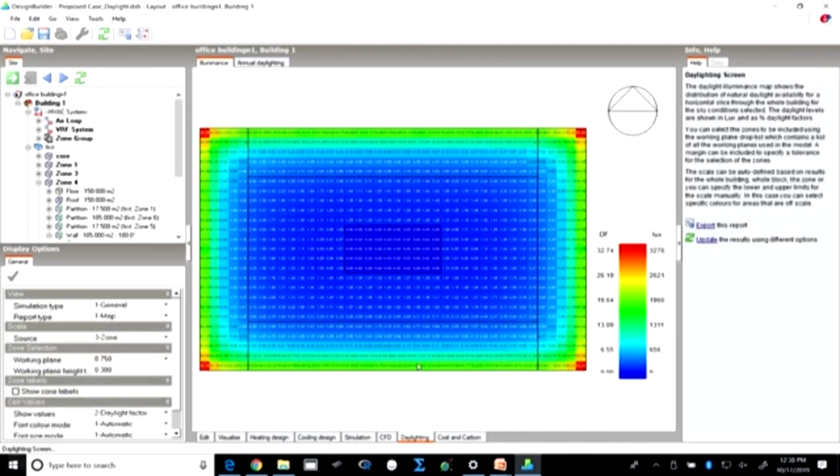If we compare the values which we had earlier, we would see that the values for the southern side have become more uniform, and a similar thing we can do if we want to change the fenestration design and the glazing specifications for all the windows in this particular building, and we can keep experimenting and comparing the different options that we can possibly have through design as well as specifications.